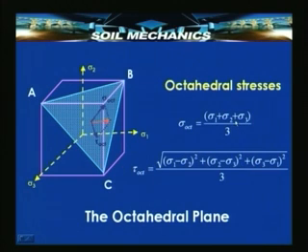And what is special about this again is, this is total stress in terms of octahedral stresses, and if you consider pore pressure, then pore pressure will get subtracted from each one of these stresses, and therefore, effective sigma octahedral would simply be this minus u, whereas effective shear stress octahedral will not change, it will be the same as the total octahedral shear stress.